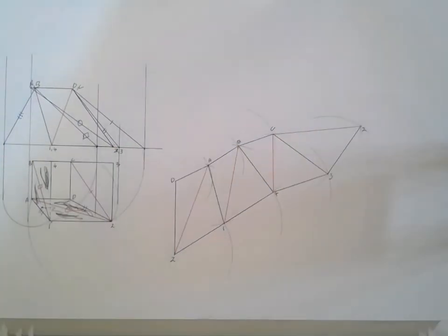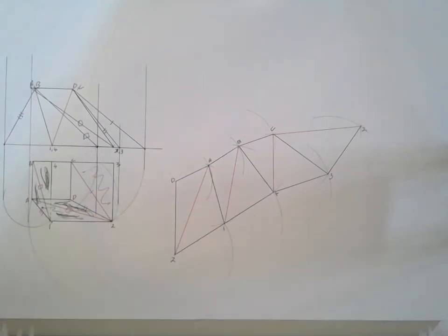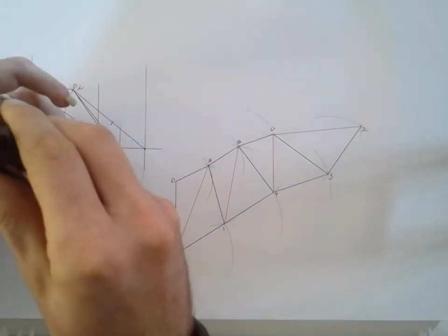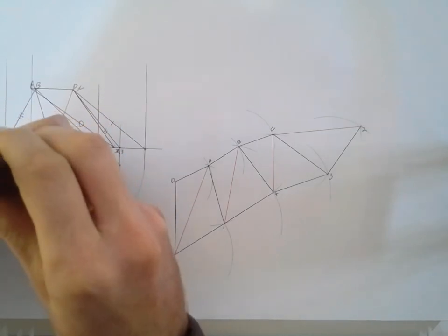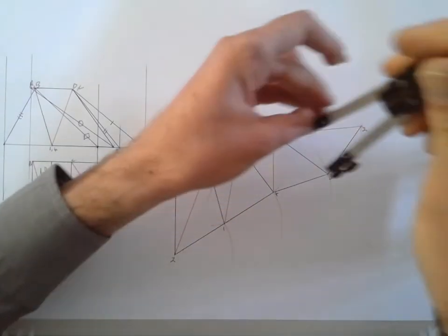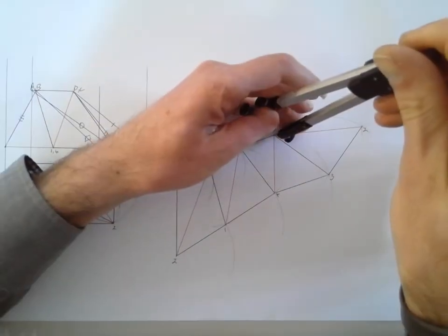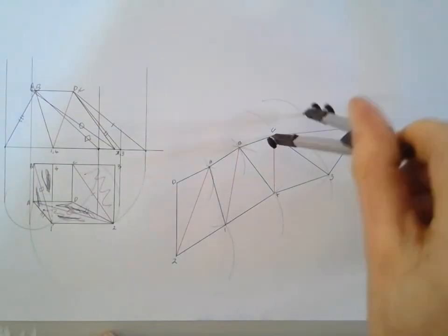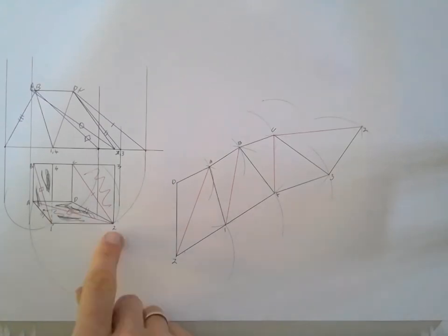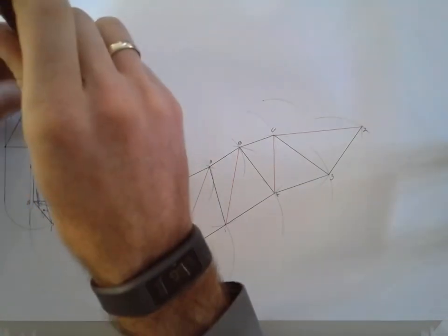And then our last triangle that we need to complete, because we've now done that one, is the triangle DC2. And for that we need the true length of CD, true length of CD. We place that onto point C, make an arc, and then we need the true length of D2, which is the line that we started with, and we can find that over here with the line that's marked with 2 lines there in our front view.